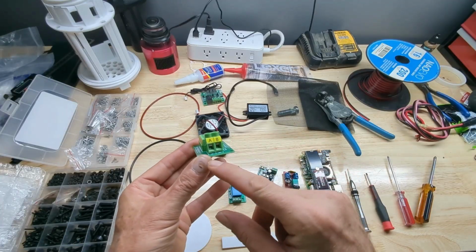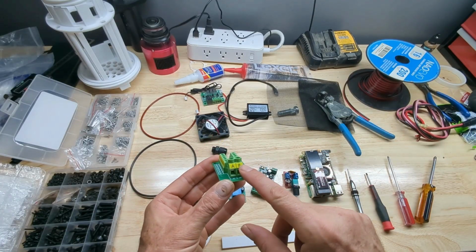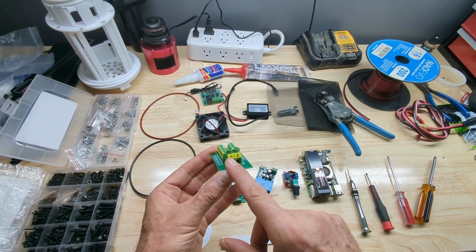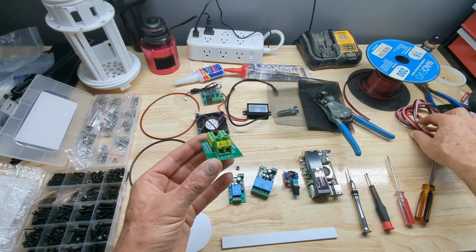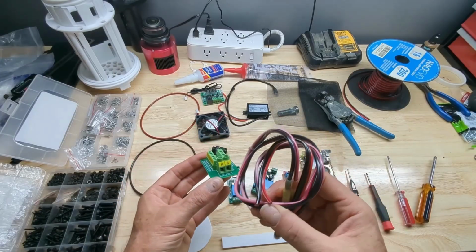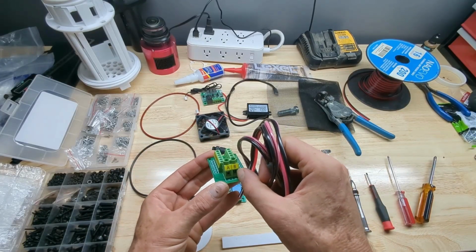This is going to be our power distribution block. So what this does is your positive and negative, you decide A or B. I always just do the positive on the A side and negative on the B side. So where your power is coming in through the bottom of your enclosure, the red will go on that side and the black will go on the B side.